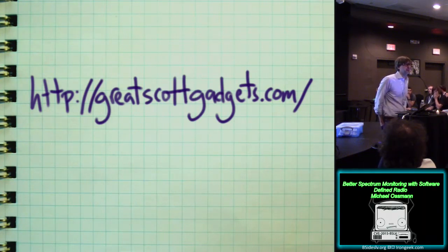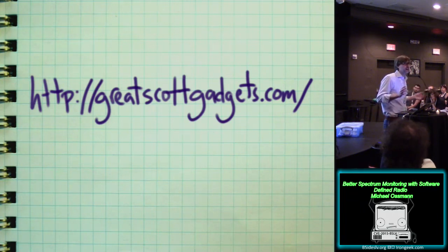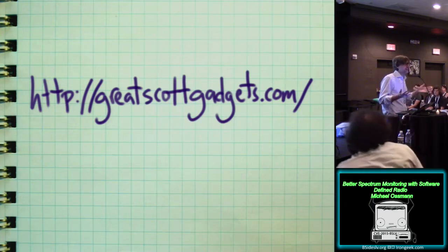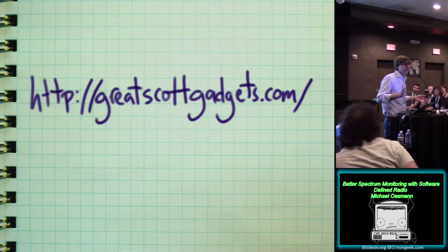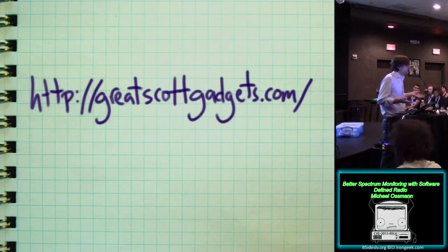I would say it really depends a lot on the very particulars of your application. There are some antenna designs that are very wide band, like that measurement that I took in a hotel room. I would have been much better off using a disc cone than using a telescopic antenna, but the difference is a disc cone doesn't fit in my backpack. So that's not what I had at the time. There are horn antennas and various designs that are specifically designed to give you a good response over a very wide frequency range. But generally speaking, any antenna only has good performance over a limited frequency range, and every antenna is different.